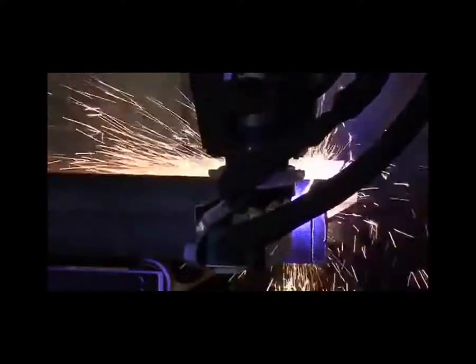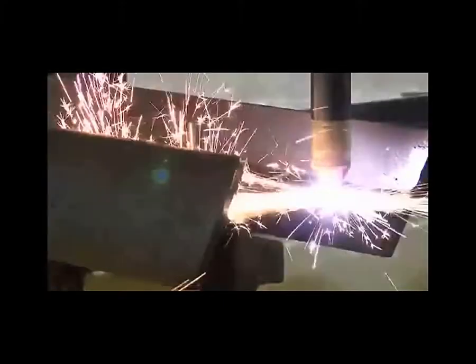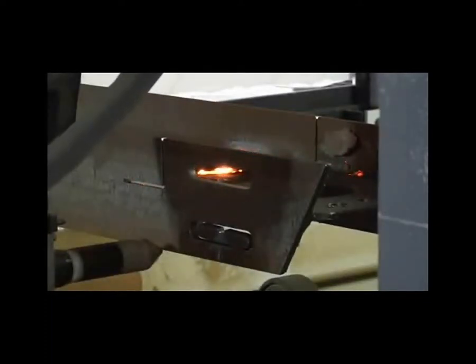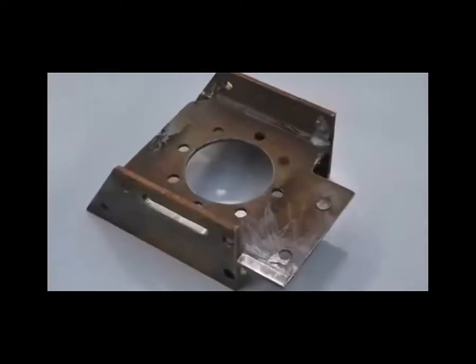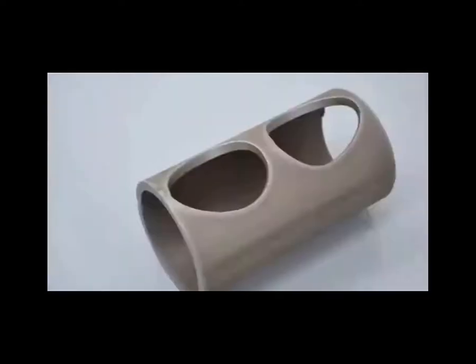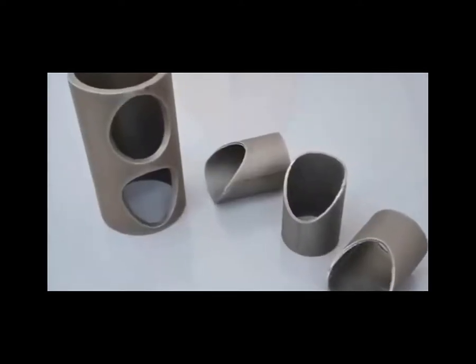As well as that, we have the three-dimensional coping. So you can see here the robot is cutting or coping these pieces as per the Tekla model again. All the instructions for slot holes, rat holes, notches on the side, all this information is passed directly from Tekla. So any cuts or copes you put in Tekla are linked directly to this plasma cutting machine. And an example of the kind of finish or information that can be passed through.